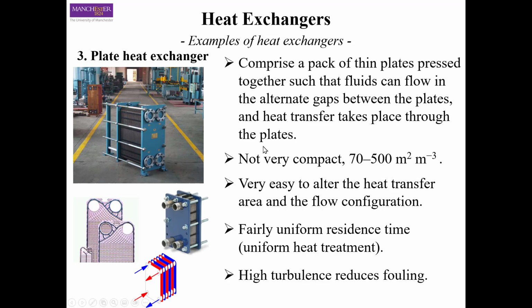Then we have the third type of heat exchanger, and that is what we call the plate heat exchanger. Here is how it looks. You have a number of plates that are very thin, and you combine these plates in a very compact form. The blue one, for example, has the cold liquid, and the red one has the hot liquid. The cold liquid goes to the second plate, and then the third plate, and so on. So this is how you exchange heat between these different plates.